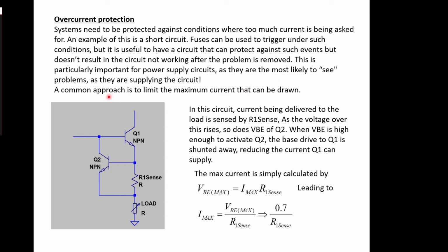We've seen in the last one that some of these systems are inherently self-limiting anyway. With a single transistor we only got a maximum of 60 milliamps out of our regulator, but then when we improved the design, we ended up with a lot more current, orders of magnitude higher potentially, of 1.4 amps or so. It could be that we can get a lot more out with even better designs, and under certain conditions we don't want to get all that current out because it's indicative of a fault condition somewhere in the circuit, so it's too big a current at the wrong time.